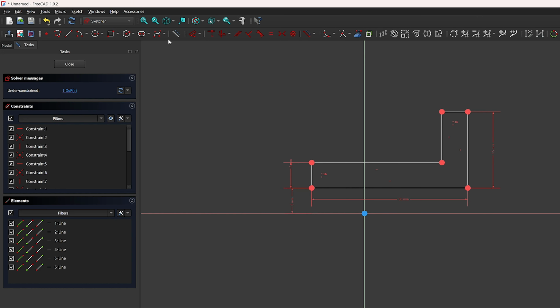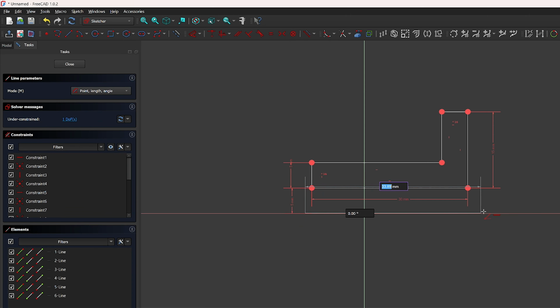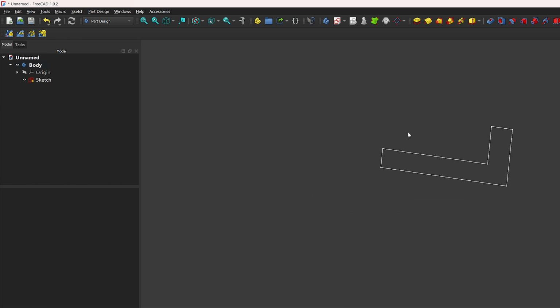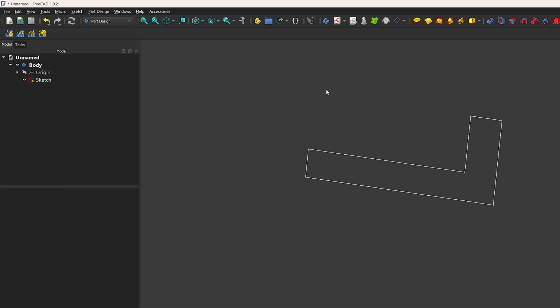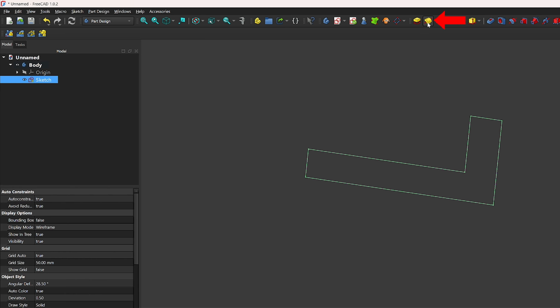The next thing I am going to do is toggle the construction geometry, and let's plot the construction axis. It is actually ideal to create your own axis rather than depending on a standard XYZ axis, because sometimes our expectation may change and then we do not want to revolve around any particular standard axis. Now after creation of this sketch, let me select it and click here on revolve.